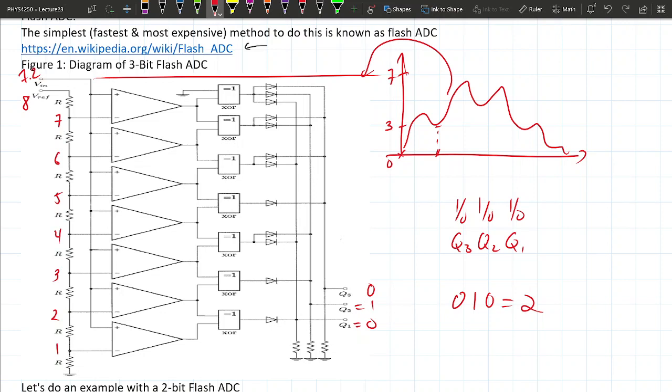But these exclusive OR gates are going to give you 0, 0, 0, 0, 0, 0, because you're giving them 2 inputs of high. Except for this very last one, where one of the inputs is connected to ground. So that's going to make this exclusive OR gate send out 1, and that's the only one that's 1. There are 3 diodes connected to it, 1 going to Q3. So I'm going to change the output of Q3 to be equal to 1.